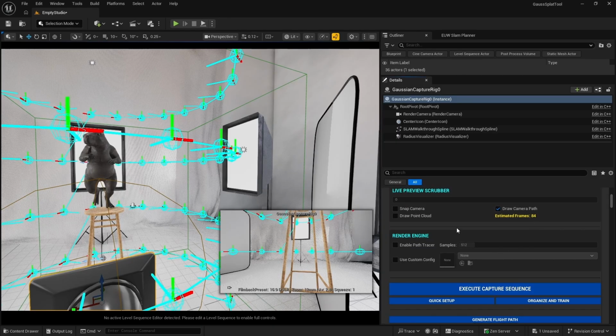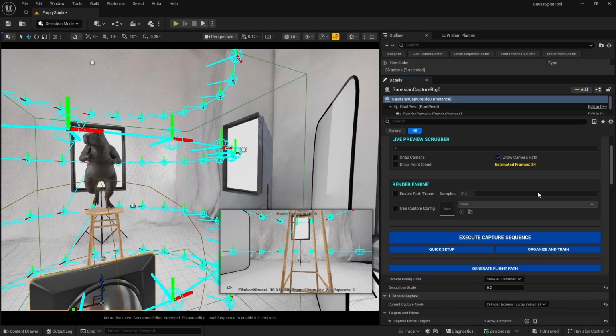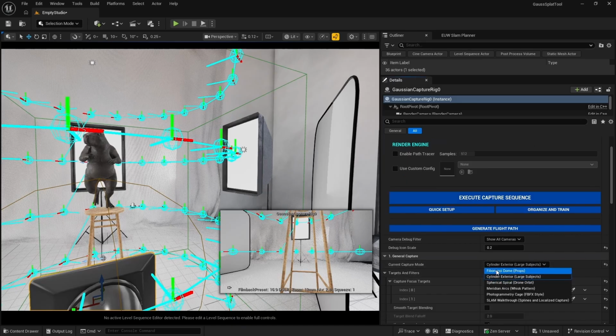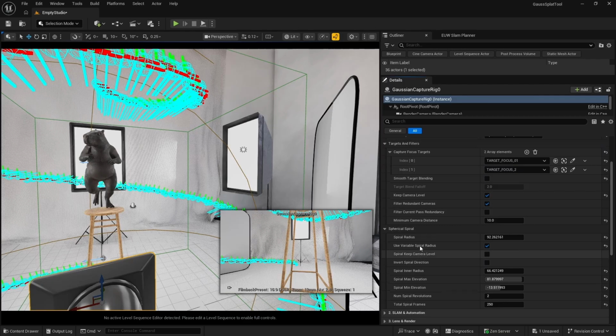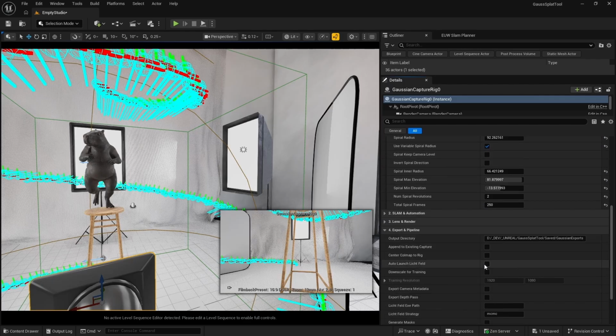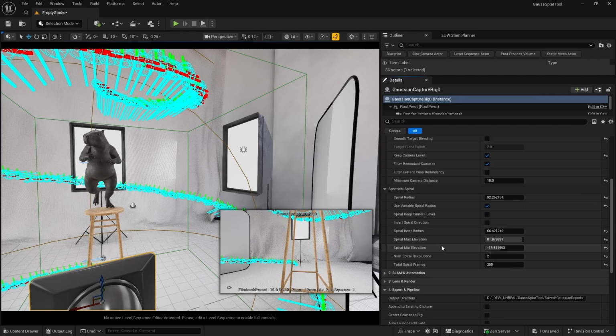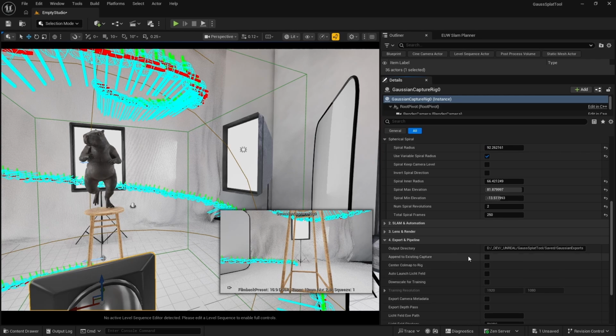But then after you capture the 84 frames, you find that you still need more data set. I mean, that wasn't enough. You still need to cover more areas. Maybe you change your method to something else, to your spherical orbits. This append option allows you to always append to the data set, so it doesn't overwrite. It always appends to the data set. So you append to the methods. The next run you append to the data set. So your data set really grows as you go along.